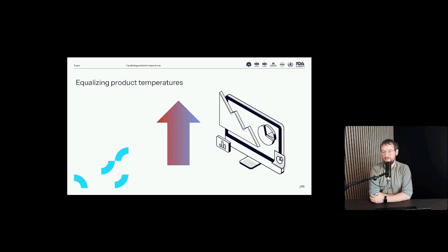So there's a question here from Smilja. Thank you very much. So to measure throughout the winter mapping period, what is the minimum measurement frequency of one data point in minutes? So it's a really good question in terms of how fast should we measure. I would often say that there is a maximum measurement interval. Most of the guidelines outline 15 minutes as the sort of maximum measurement interval. But we would always recommend going for a maximum of 5 minutes.